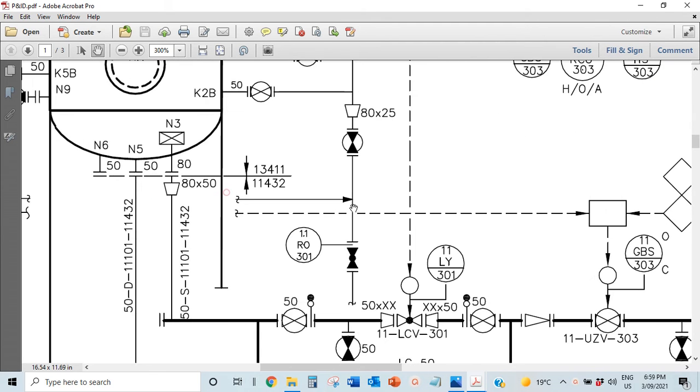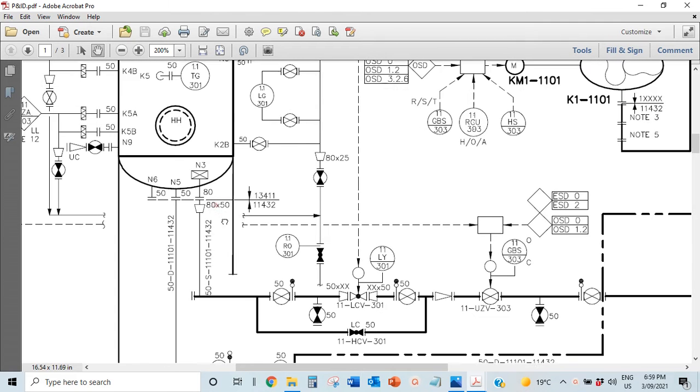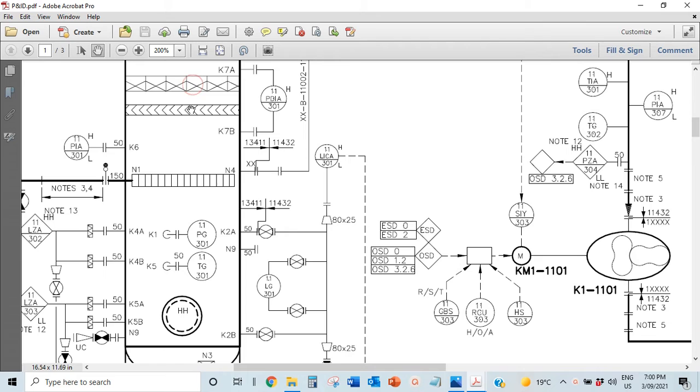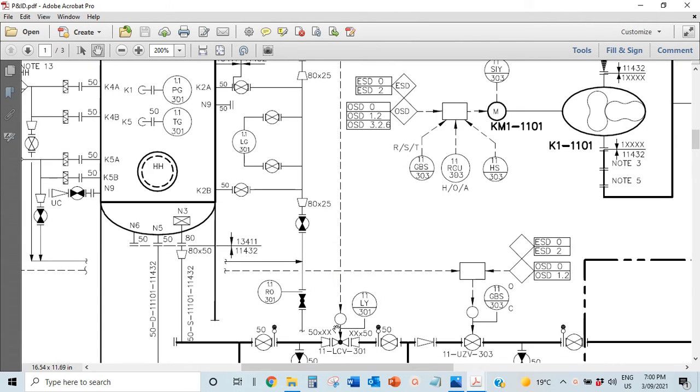The difference between this and the shutdown valve is that this is trying to control the level of the liquid in here so that it doesn't go so low that it's empty, and it doesn't go so high that it's too full. That's why it's connected to this high and low. So this is controlling this. The flow just goes up, goes down. If the liquid in this is too much, it opens up and more fluid goes out. If the liquid in this is too low, it closes so that you don't have an empty vessel, because then you would have a gas blow by.